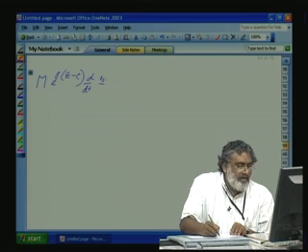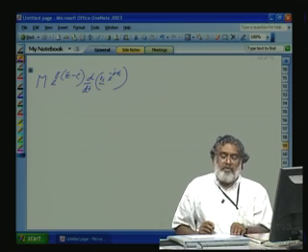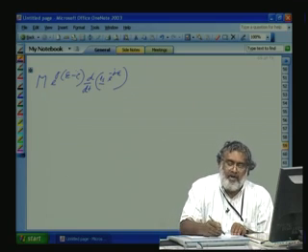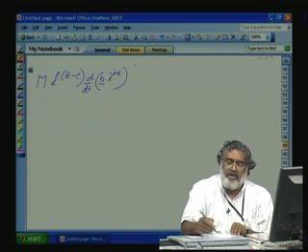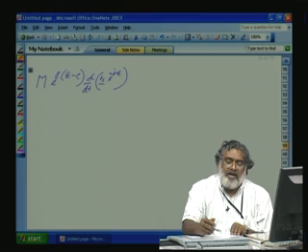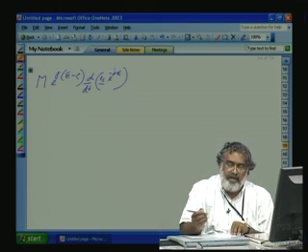Now, the component of this one along the rotor axis will be equal to e raised to minus j epsilon. So, this is the voltage term M into d by dt, e raised to j, e raised to minus j epsilon. This is the voltage term induced in the rotor. Okay. Now, this one we want to transfer to the stator axis.